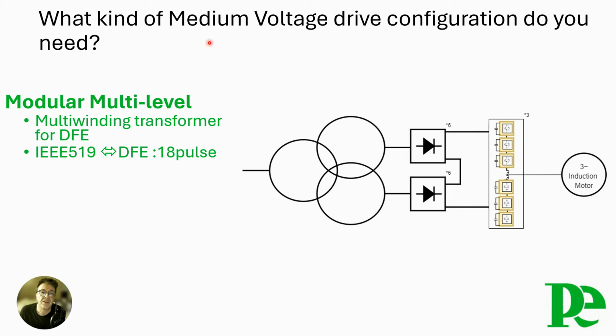This drive provides a superior sine wave output and voltage, effectively eliminating the harmonic heating and insulation stress on the motor and significantly reducing torque pulsations. For these reasons, this drive excels when the existing motor is to be reused for revamping purposes.